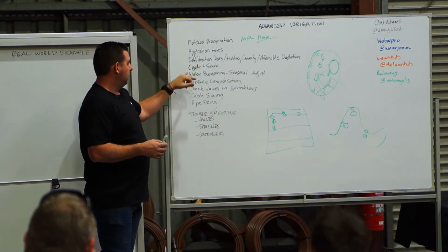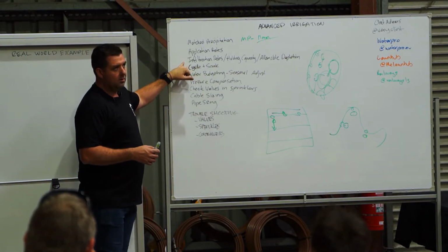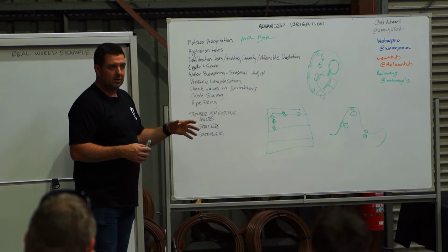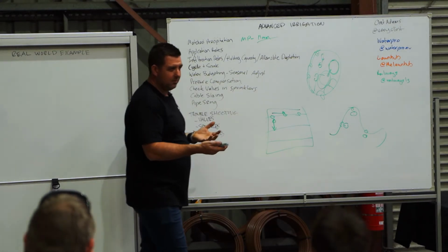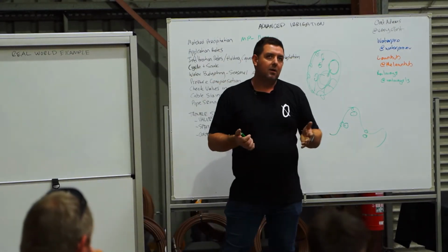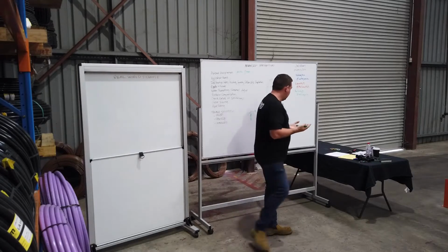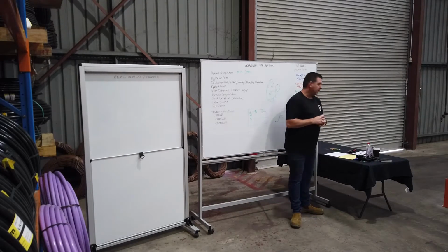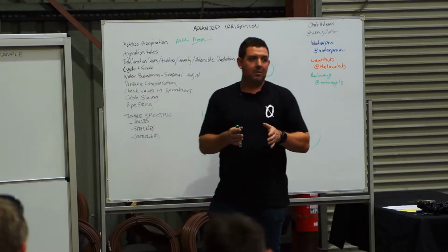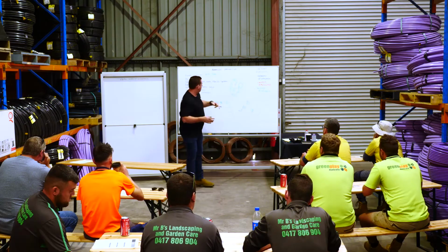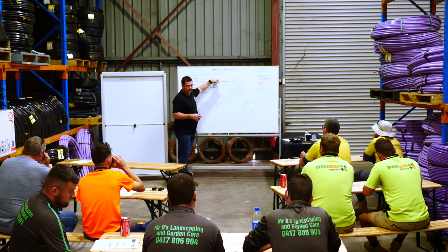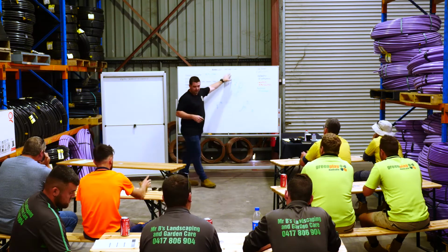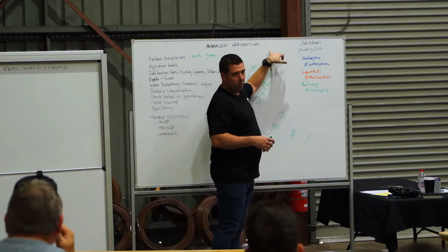This is something that you've probably not moved into yet. If you've got a soil type like a clay loam, it might be capable of taking 5 to 10 mil an hour. And then you've got a product that puts out 11 mil an hour, or a product that puts out 14 mil an hour, or a product that puts out 20 or 30 mil an hour.